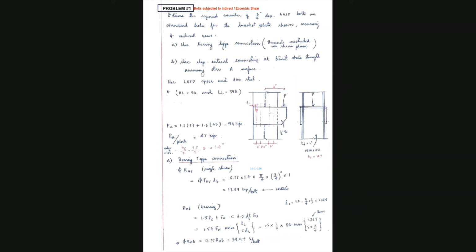You can just draw a small figure here. Suppose this is the flange and this is the plate, and you have a bolt here. Now the only shear critical area is just this one, because your bolt is in shear only in one plane. That is this particular plane.